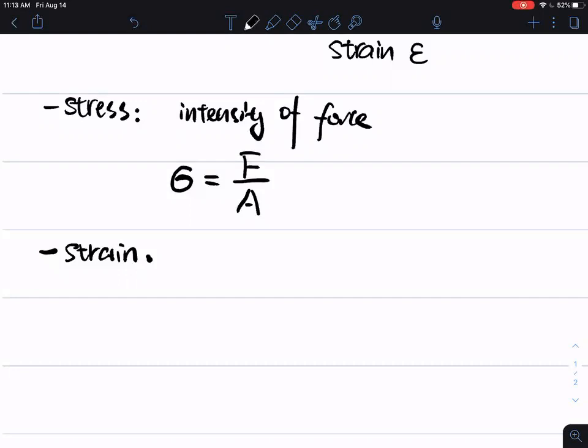It's really tiny. But what if I have a piece of material that is only 5 millimeters long, and I tell you there's a 2 millimeters change of length? That could be very significant for just that 5 millimeters, right? That's 40%. But that gives you a sense. If you only use change of length, that's not enough to describe if it is large.